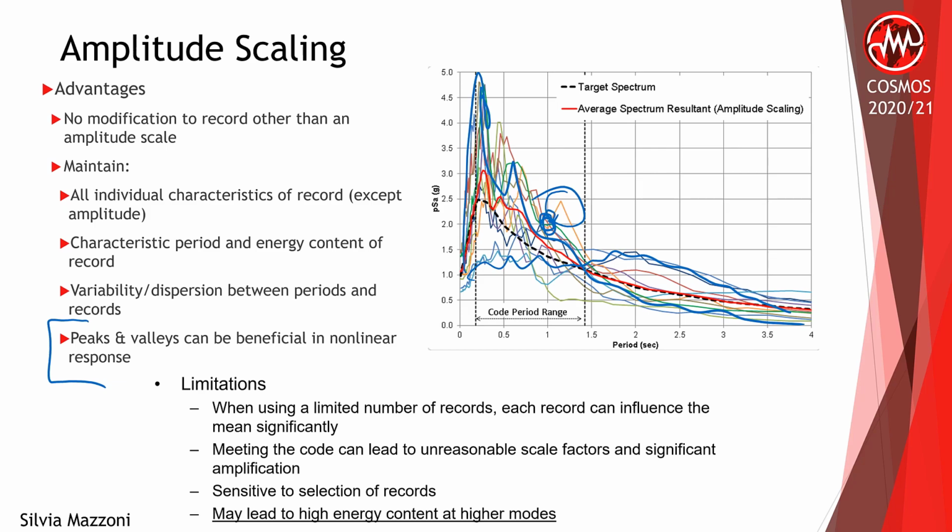If you're at a trough here, it gets interesting because as you have yielding, now your demands actually go up, and that's realistic. They're not going down as they would be if you have a regular spectrum or a modified spectrum. Remember that whatever you have here, the behavior is different on the other side of the peak, okay? But it's hard to see it because I'm plotting a linear plot.